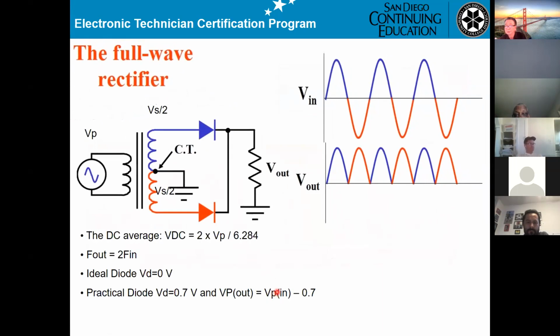Okay, now we go to full wave rectification. If you're looking at the output here, you can rectify this in a full wave. Half wave rectifies only positive, not negative. However, this circuitry rectifies both. That means when you get positive, you get output. You get negative, you get output. That's what they call full wave rectified. They rectify both the positive and negative of the sine wave.